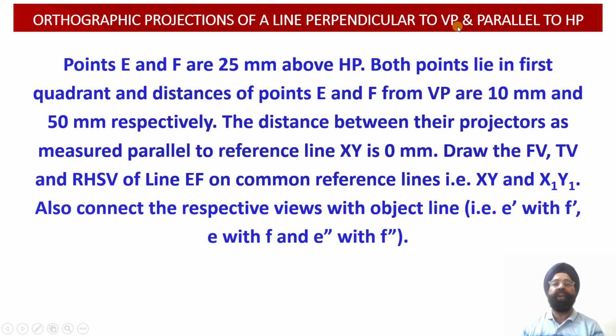So this line will also be parallel to the profile plane. Therefore, we are also going to obtain the true length of the line projected onto the profile plane, in the right hand side view of this particular orthographic projection. So let us read out the statement.